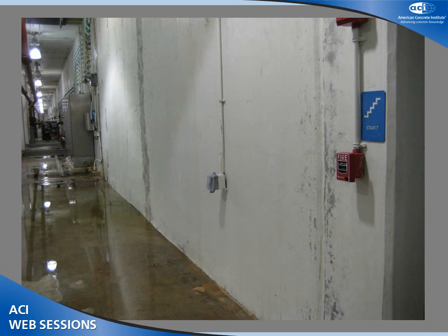There are very few owners that would like to have a brand new tank built, and then this is not a polished concrete floor. That is standing water as a result of cracking in this wall. That wall was approximately 2 feet thick, full of reinforcing. There were some issues there in terms of the joints and spacing of joints, execution of joints. But this is what we're talking about for serviceability.